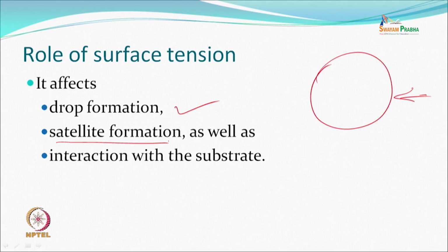So an optimum level of surface tension is required, because finally we want a drop to be spherical, and we want the dot to be a circle, a dot which is going to be created on a textile substrate. And you can appreciate that surface tension properties would determine whether the drop will very easily spread or just stay where it is before it is dried.